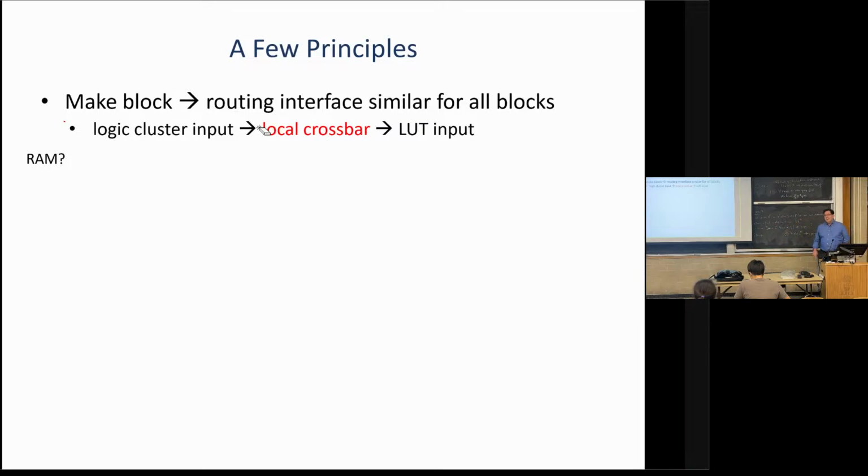Your data bits you can, but you have to do it for both the read and the write, so it gets kind of messy. If you flip your data bits, you could say, I don't really care which bit I write to in the RAM, just write to one of them. That's correct, as long as you make sure you do the same thing on your read path. So there's some flexibility there, but it's kind of a mess to try to take advantage of.